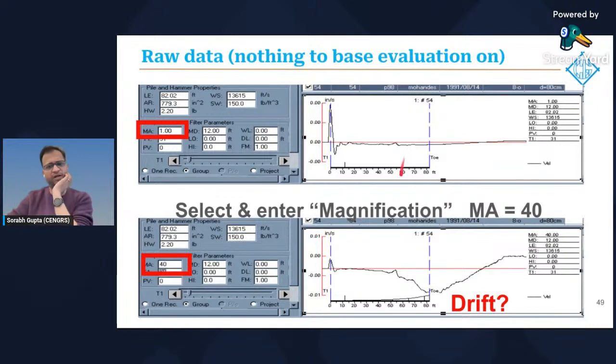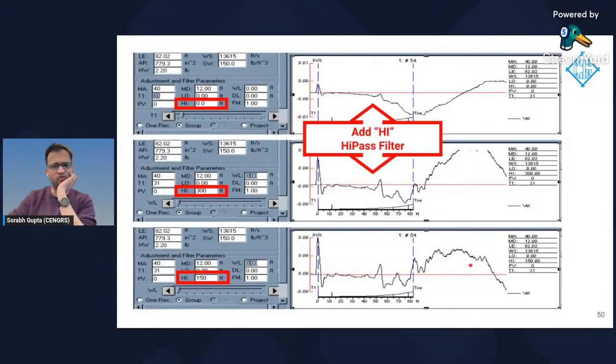But you observe here that when I magnified the data, I got some drift in my data. It's not really going along the x-axis, it's drifting. So let's understand this and what we can do to fix the drift. The reason for the drift is likely that below around 50 feet, sorry, this is in feet, we have some high resistance soils.